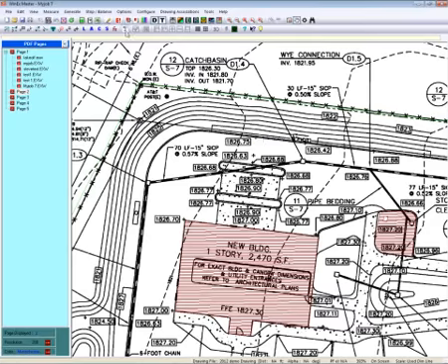And if I were to go up to my Edit menu, just to make sure this has the same subgrades as this, if I go up to my Edit menu, which is this big red E with the exclamation mark, when I click on it, you'll see a whole new toolbar come across. And I can actually delete something, change the color, change the elevation, change the description, change the subgrade attributes. I could even change the layer on it.